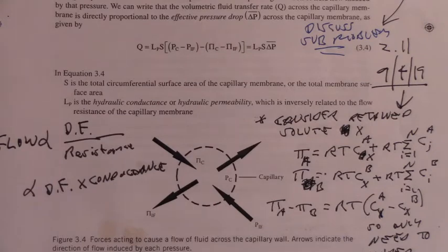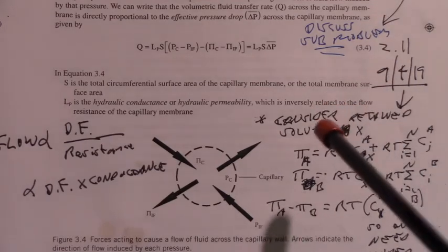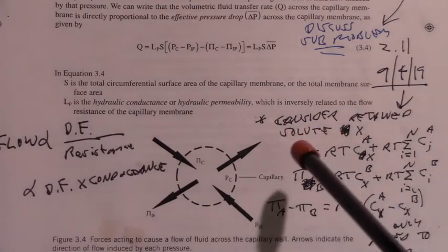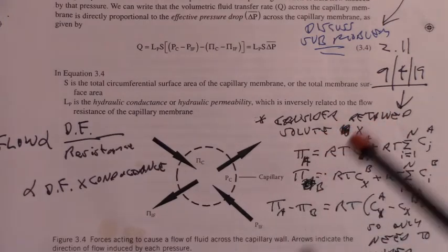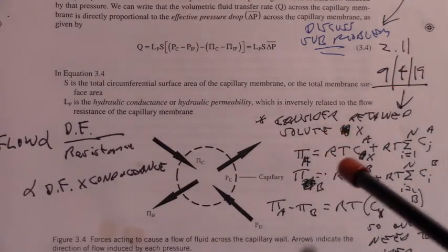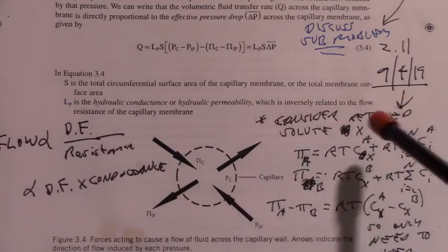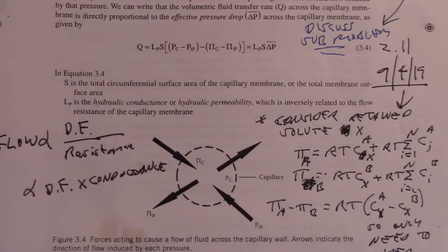But when you're looking at transport across a semi-permeable membrane, where there are species that can cross the membrane, the osmotic pressure difference itself can be based strictly on the ones that are retained. And the math for this I've laid out here. Consider retained solute X right here. So we have one solute that's retained, and then all these other solutes in the solution.